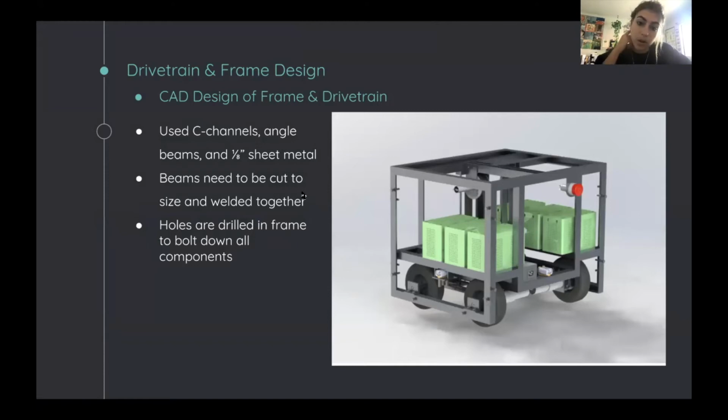The screen capture also allows you to see the internal arrangement of all the systems. You can see the striker, transducer, and actuating system that we'll go into a little bit later, but you can also see the electrical components that are powering the robot. As you can see, the batteries are distributed across the center axis evenly. This is to prevent the robot from tipping over during its motion. All of the electrical components also have custom housing so that they can be protected and easily mounted to the C channels.